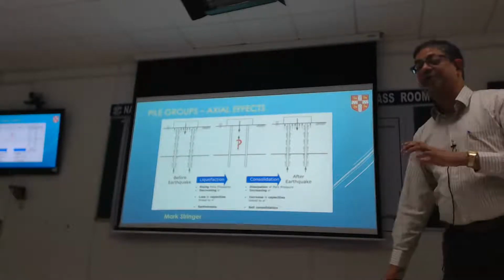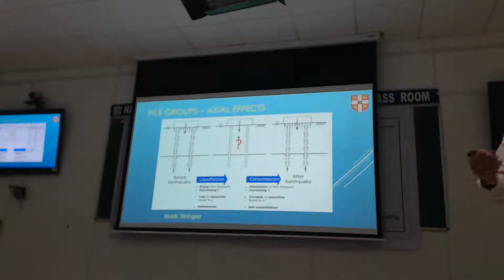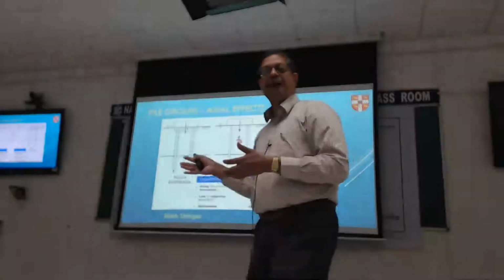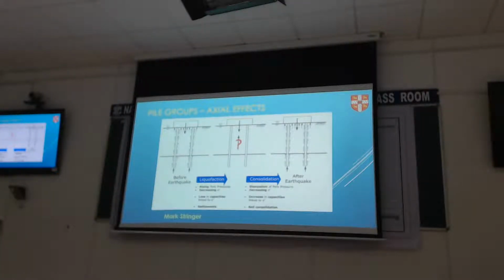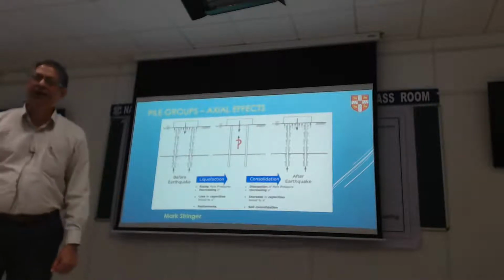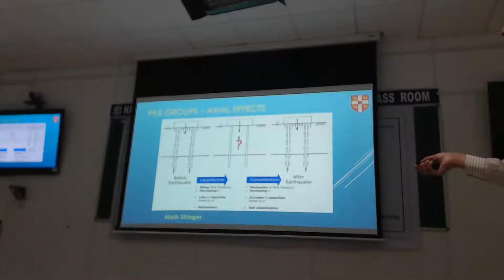What's not clear, sorry, there's another point. Structural engineers, quite rightly, don't believe us about this pile cap capacity. They said the soil is too shallow. You guys may work out your silly bearing capacity calculations, we'll ignore that and consider it an additional factor of safety. So whenever you design pile caps, I'm not talking about piled rafts, only pile caps, the pile cap capacity is almost always ignored worldwide. It's not just us. Everywhere in the world, they ignore that and say, yeah, that gives us some extra capacity which adds to our factor of safety. Okay, so that is the static situation of design before you start.